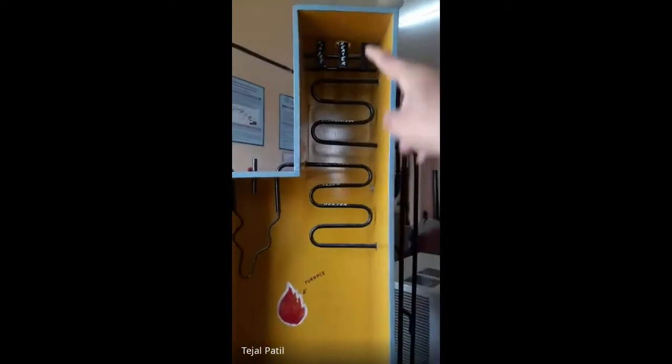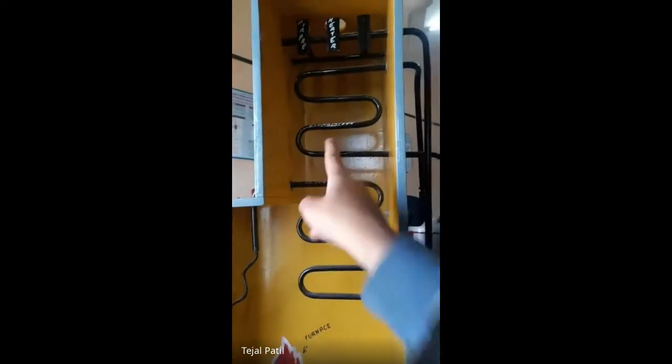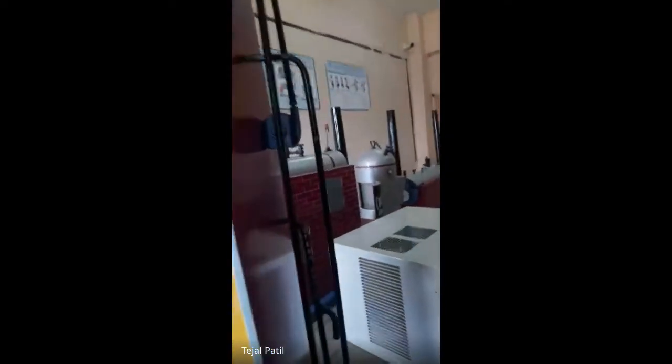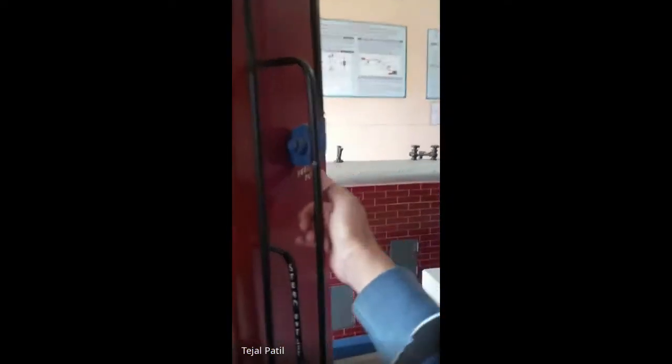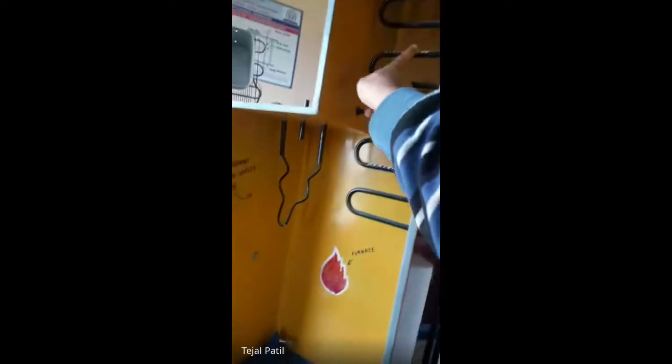Then after that, this is basically the entry of the preheater. Next, you can see this is the economizer. Before the economizer, let me show you that this is the pump, the feed pump, the boiler feed pump. What it is going to do is take the fresh water, and that fresh water will be pumped by this feed pump and sent into the economizer.